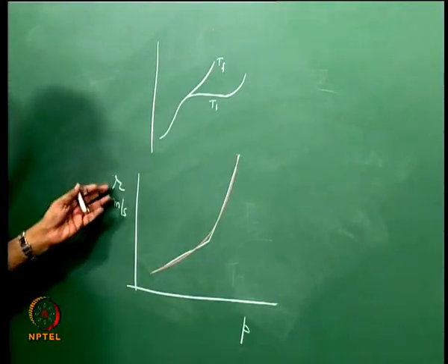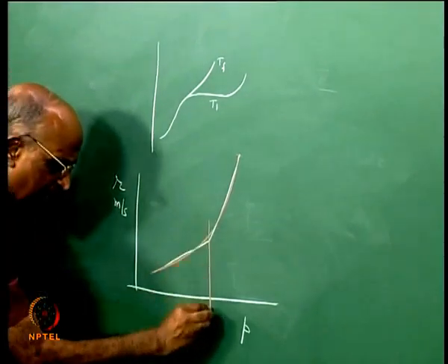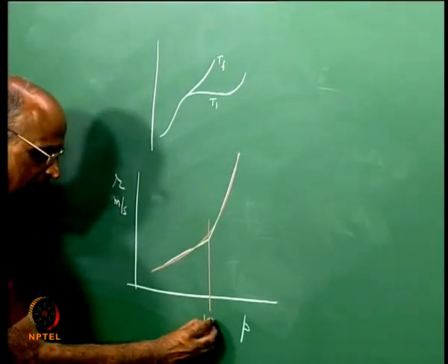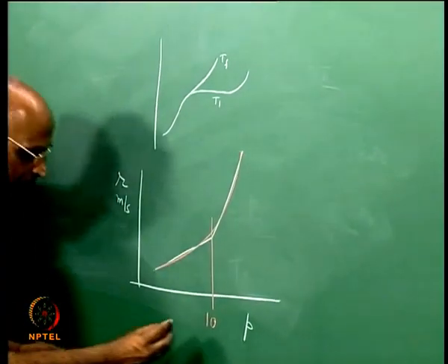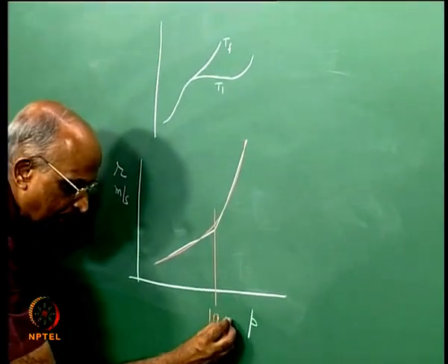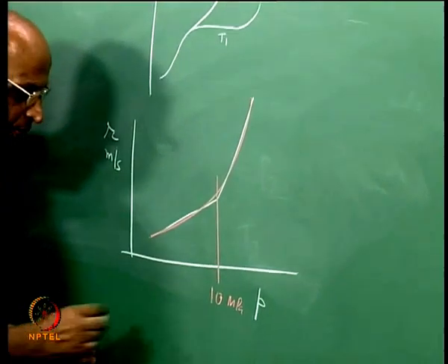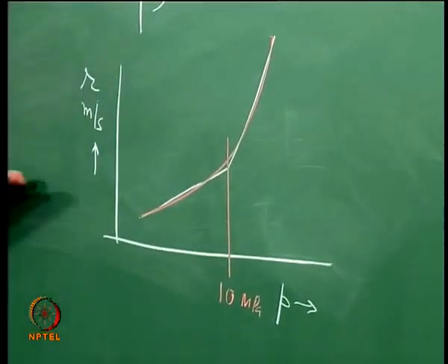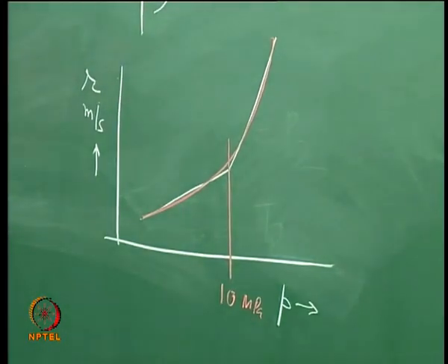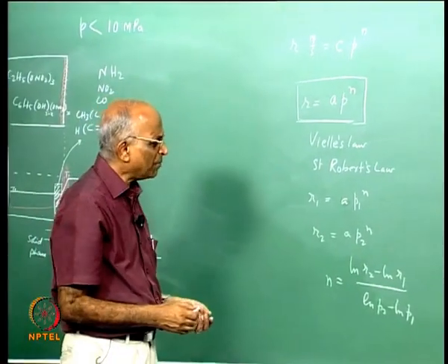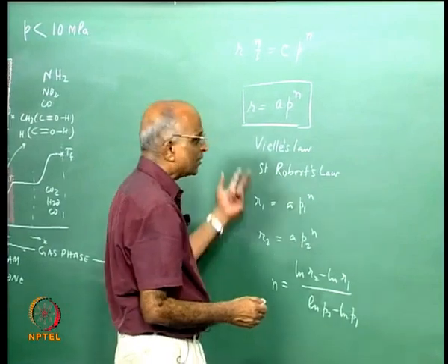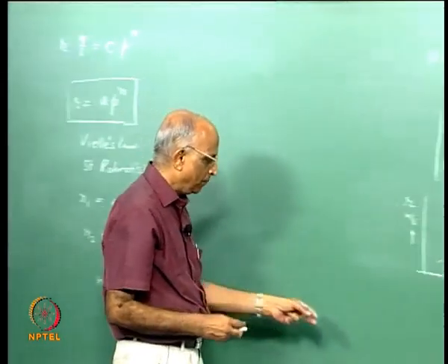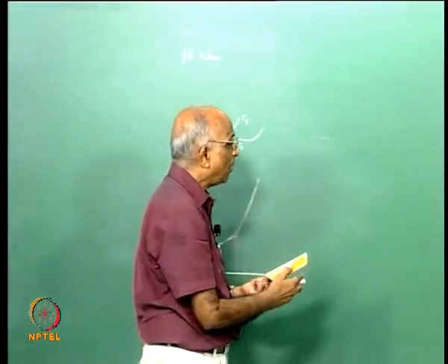This is how the burn rate varies with pressure. This pressure corresponds to where the dark zone becomes absent, something like 10 MPa over here. This is the plot of pressure as a function of burn rate. This is how burn rate is expected to vary. But it depends: sometimes when you add something like lead salt to the propellant, the burn rate is not marked like this.